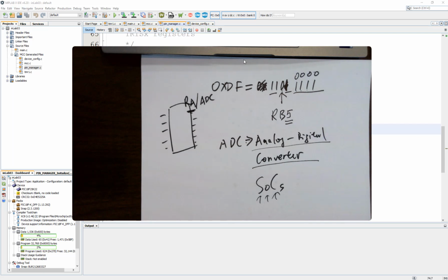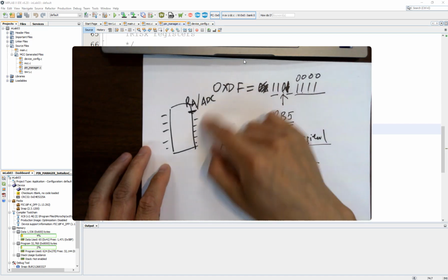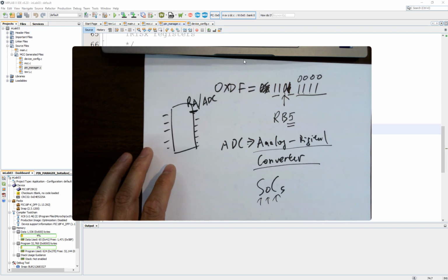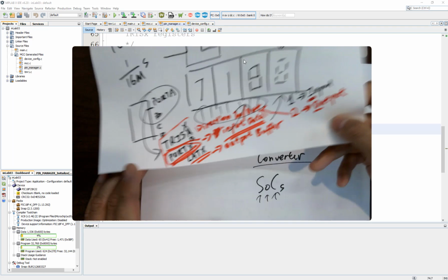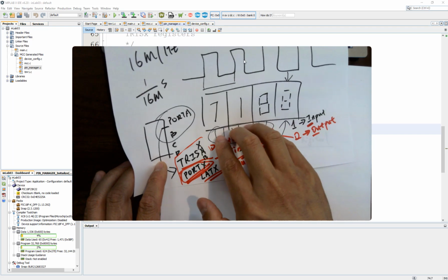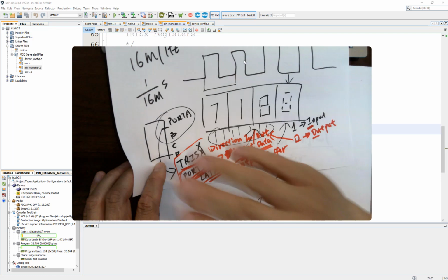And why do you display something? You want to sense the temperature and display it. And the temperature sensor takes another 5 pins. You're running out of pins. So you can either use a decoder or something, but that's something else we can talk about. There's another shift register, called the 595, that you can use to shift all the bits to the data pins, which will save you a lot of pins.